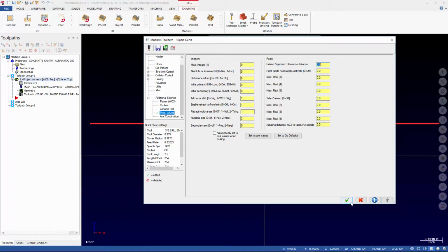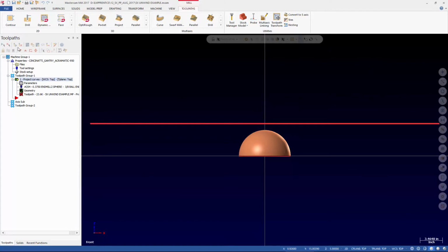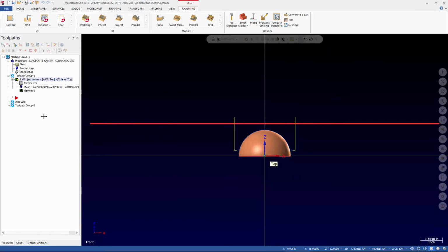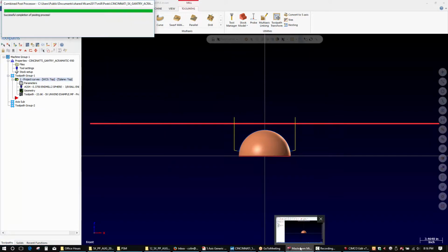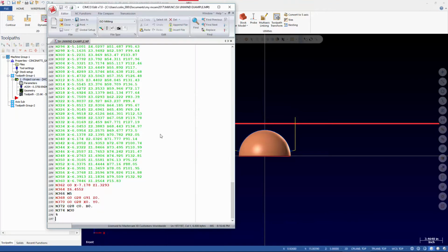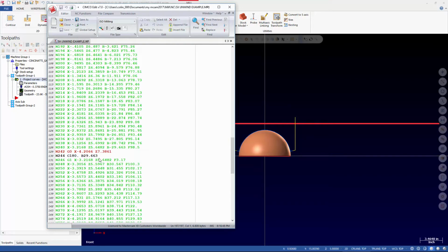And I think the default is like a 2-inch or 50 millimeter retract. So that may not be close enough. Just fair warning, that default value is pretty small. So here, we're only making like a 2-inch retract move, then unwinding, then reapproaching.